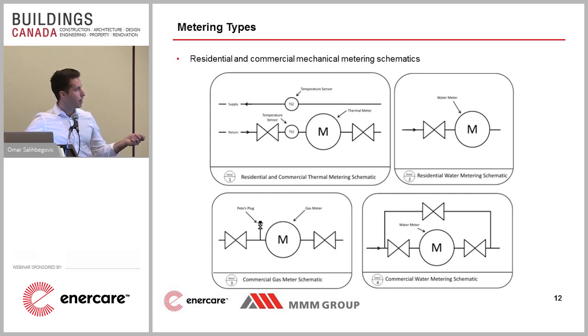And you'll see at the top here, in the top left-hand corner, that's an example of our thermal metering schematic. So you have a flow meter, which we usually install on the return pipe, and you have two temperature sensors, one on the supply, one on the return.